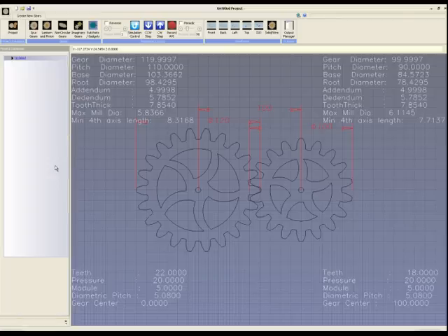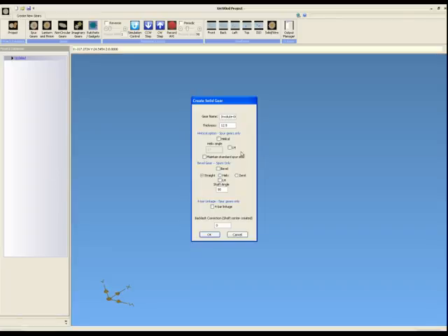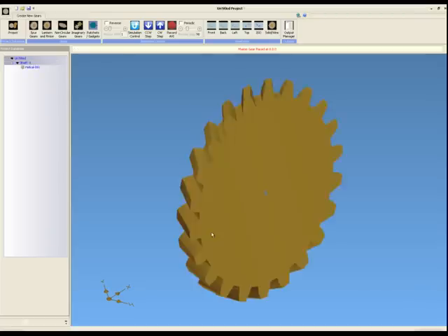If we hit Add Master to Project and we accept our first helical option, check the helical box, and we're asked which helical angle we would like to use. Helical angles can go from 0 to 45 degrees and are specified as left or right-handed. If you don't select left-handed, you are obviously right-handed. In this case, let's just select a 45-degree helical and leave the left-hand box unchecked, which gives us a 45-degree right-handed helical. And there we have it on the screen.